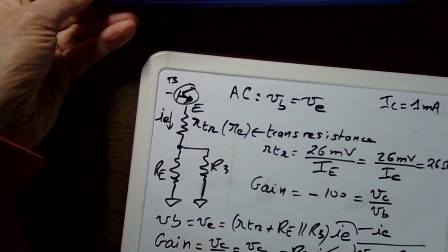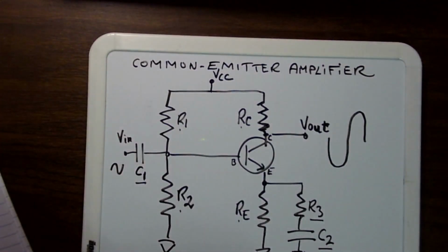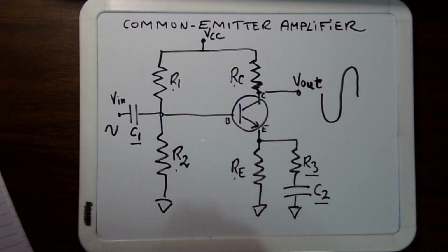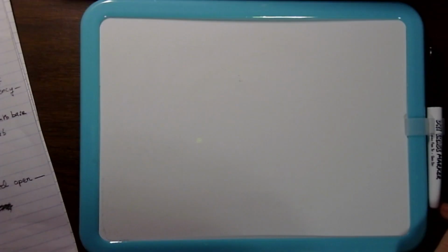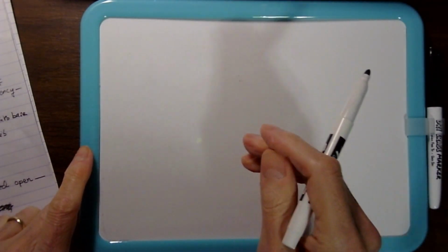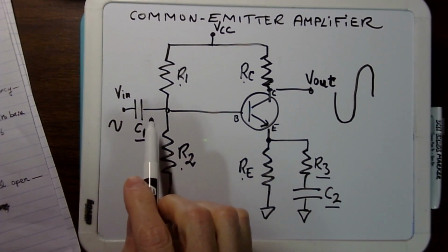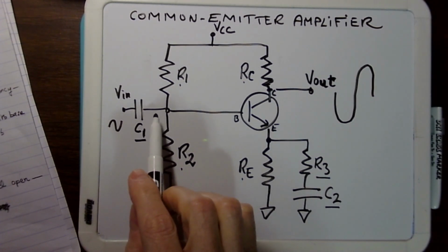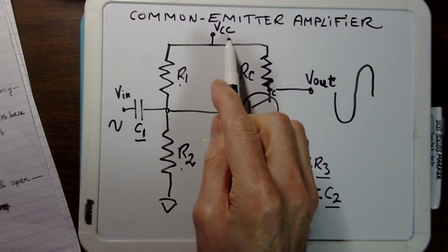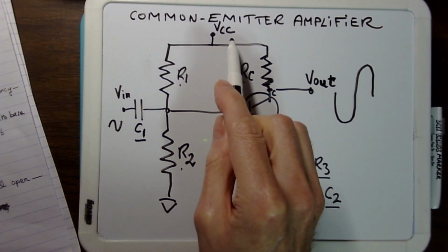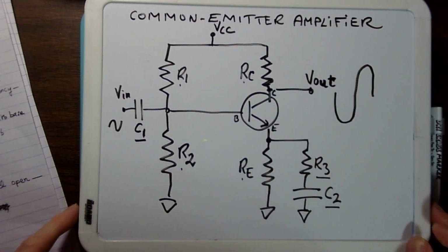So what's next? What's next is the capacitors. The capacitors, we have to do that. So we just got R3, so let's compute C1. Let's redraw that circuit. This is the circuit. But because we are doing AC analysis, VCC is actually a ground. It's a constant voltage source, so in AC analysis, it becomes a ground. So we can redraw this thing.